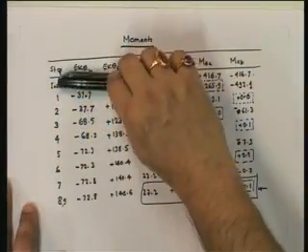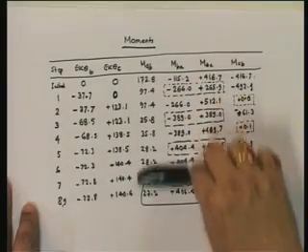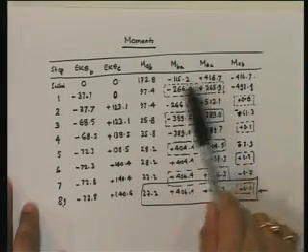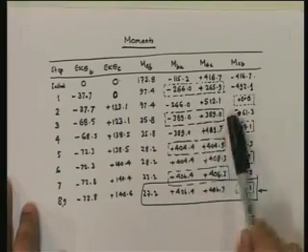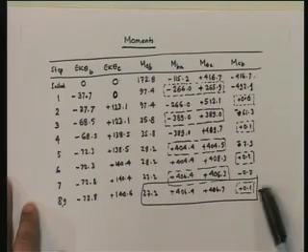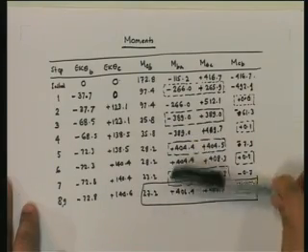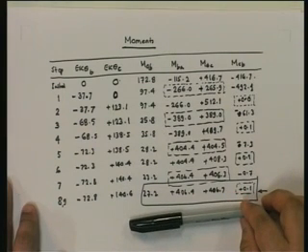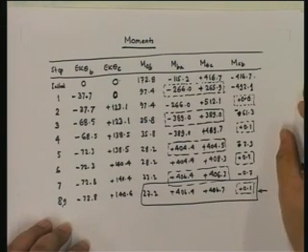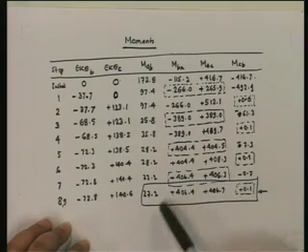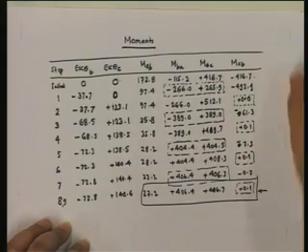So although we looked at it as Gauss-Seidel, this is the Gauss-Seidel iterative procedure. When we look at it in terms of M's, what do we get? We see that it is essentially distributing unbalanced moments at all times and ultimately getting to a situation where all moments are balanced, there is no subsequent distribution because all moments are balanced where they are supposed to be balanced. Note that here you have unbalanced because it's a fixed end. A fixed end can take a moment, whereas you cannot have an unbalanced moment at B and you cannot have an unbalanced moment at C. Okay? So now with this background, let us try to see what the method actually is.